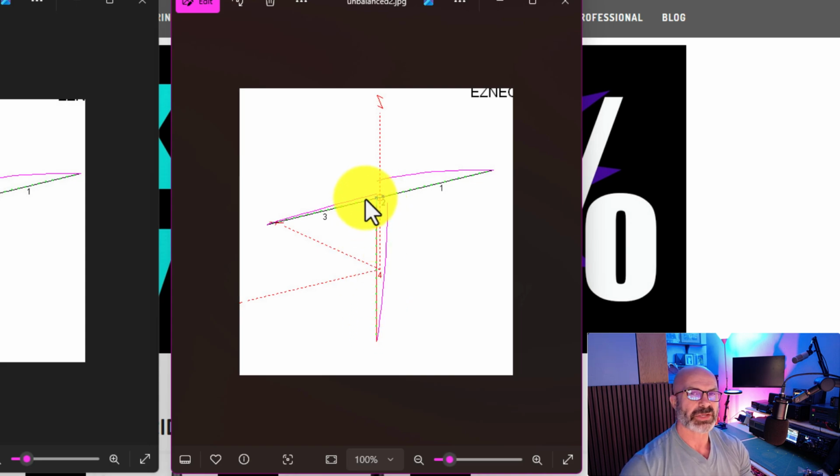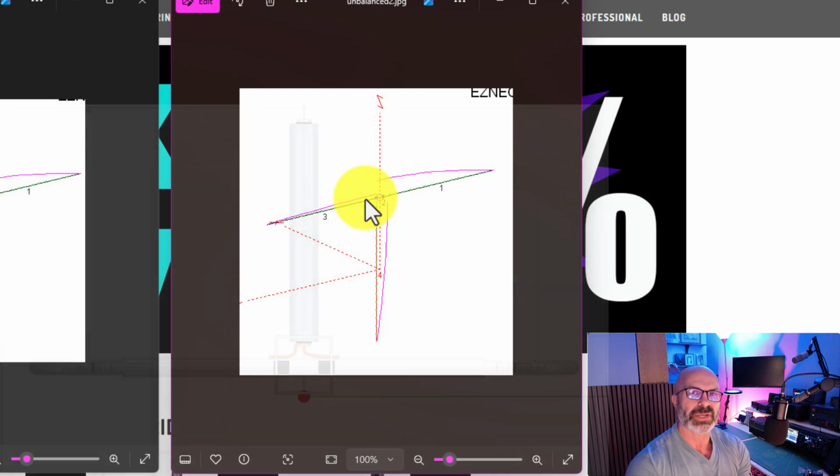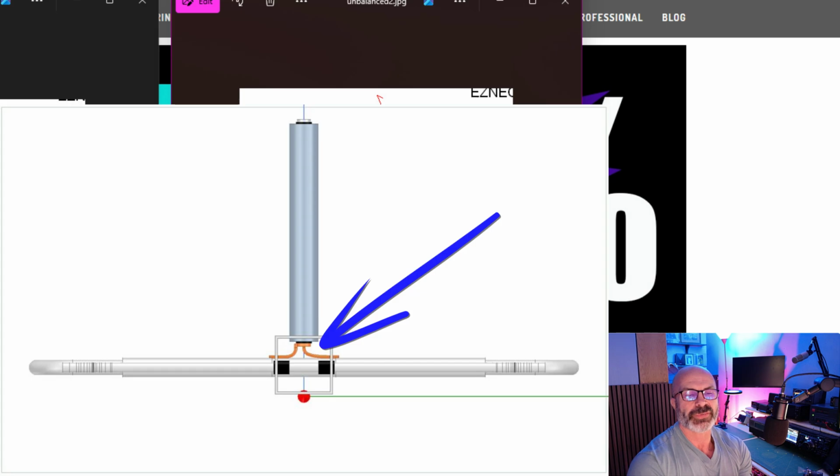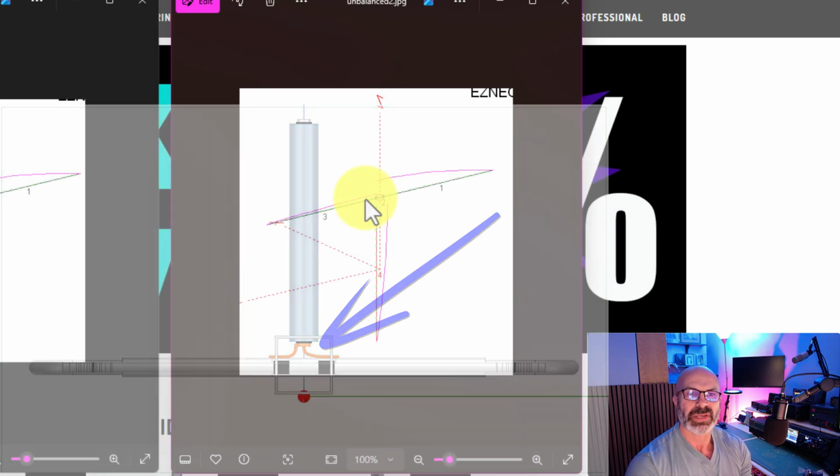And as I said in the last video, when you look at coax cable where it splits, the point where the coax actually splits and is no longer coaxial is where your dipole starts. RF doesn't wait until it gets to the terminal connections, and that's why we have to eliminate that Y shape as much as possible and make a T shape at the feed point with the coax connections here. Now with the inner core of the coax, of course, it's a nice hard and fast rule where the driven element starts and coax ends, because it's either exposed or it's enshrouded by the braid. So there's no issue there.